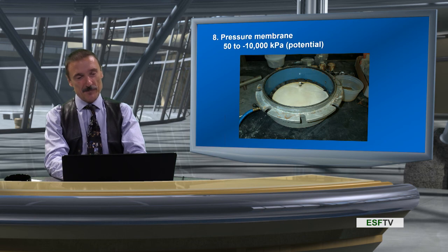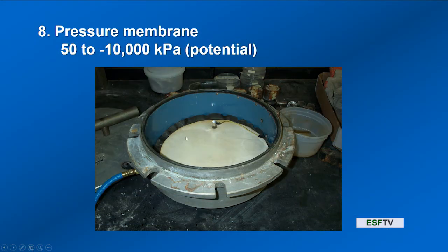So essentially it looks like a big pressure cooker, and this is a permeable porcelain membrane, and you put a soil sample on here and seal it in, and then you apply a pressure. And so you can apply 15 atmospheres of pressure, usually compressed air, compressed nitrogen, and the moisture in the soil equilibrates with this pressure.